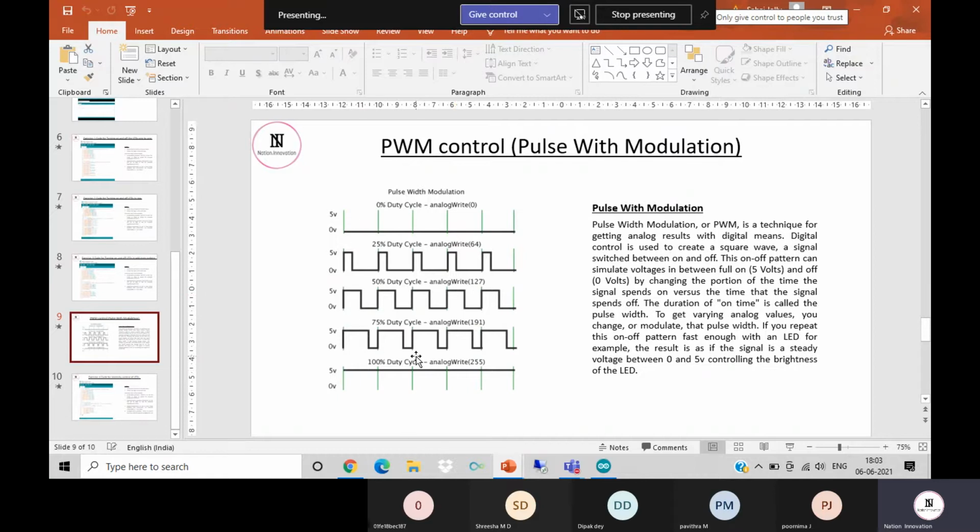When we consider the normal digital pins, like pin number 0, 1, 2, or 4, or 12 or 13, when we put a low in the digital write section, they put a 0 volt supply at the pin. When we put a high, they give a 5 volt supply, which is the 100% duty cycle, or a 0% duty cycle. But in order to control the intensity level of the LEDs, what we require is to change this duty cycle. Fine. And in this case, the PWM functionality will be helpful for us.